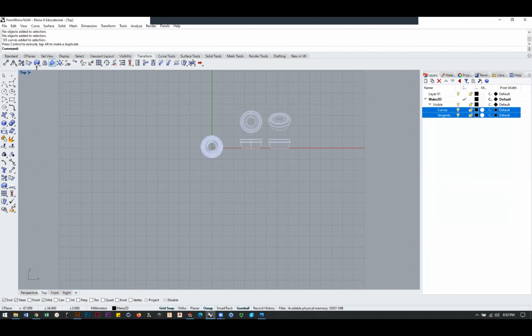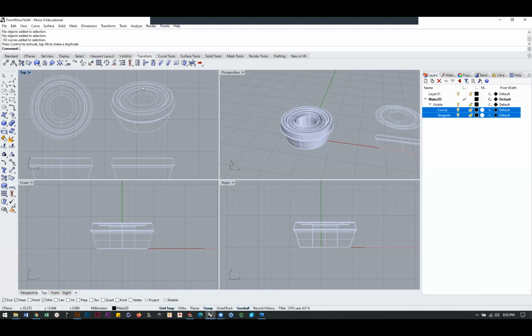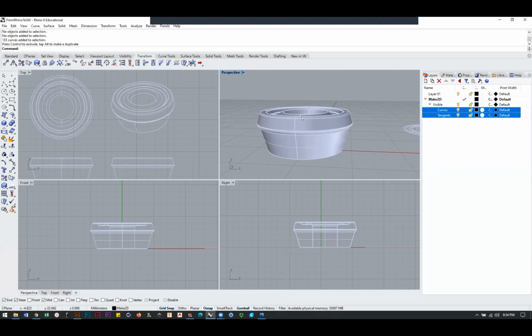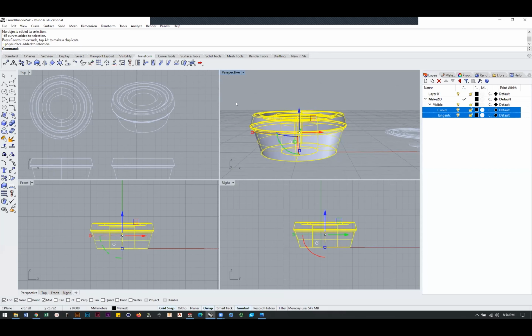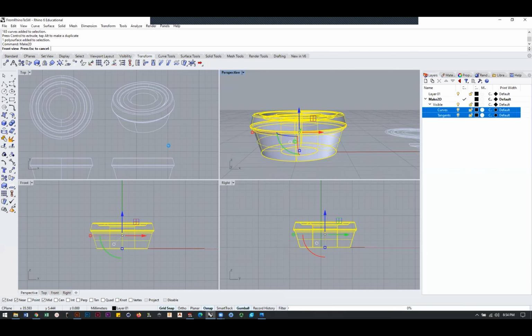I think it's a cool fact about this tool here. If you don't love the 3D angle that is created with this other set of line work, then you can change it by just changing the view of your model here. So say you want a much more flattened out perspective here. You just look at it in that view and then select the model, and then you go make 2D, set it to third angle projection, say okay.